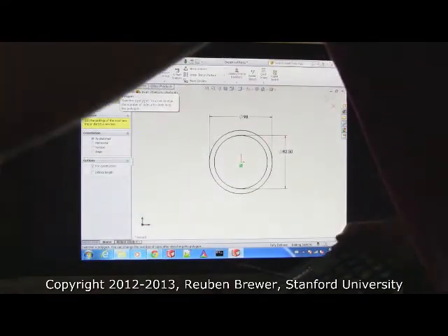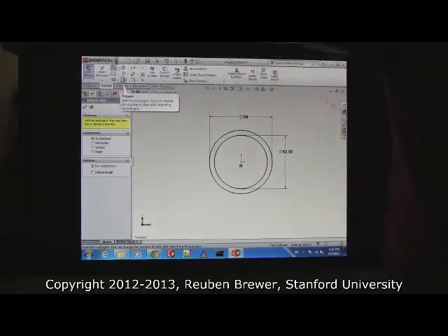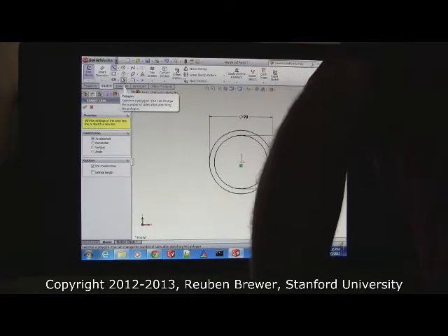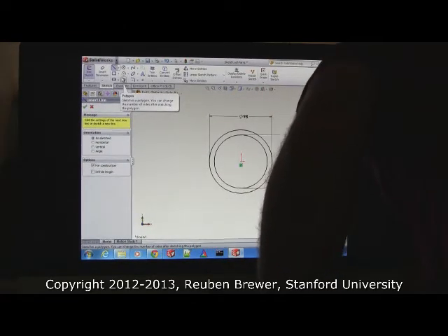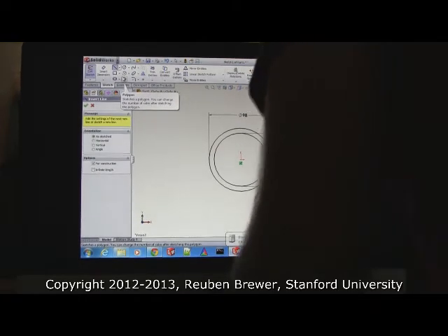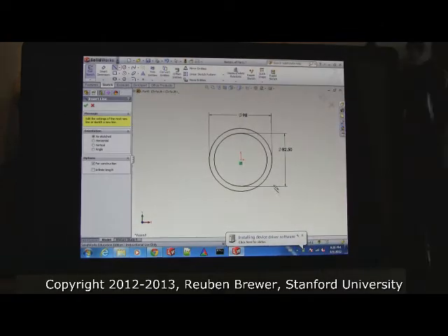I have a question for you, Ruben. So, how do you get your diameters to appear above the part instead of literally along the diameter line? Like mine, like the 98 and 82.50. They're in between the part. Like if you have a line that represents the diameter, it's on that. It's all about dragging it around once you've made the dimension.